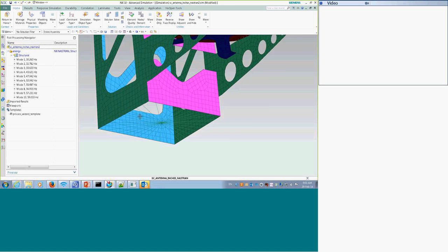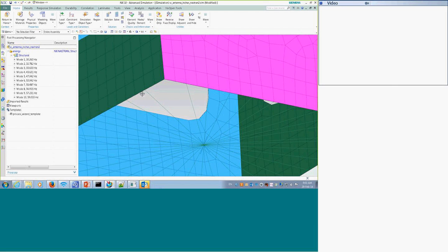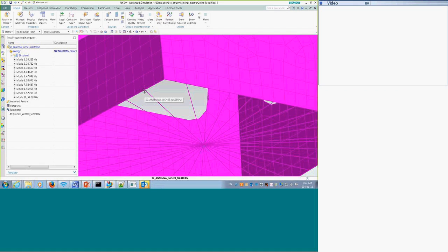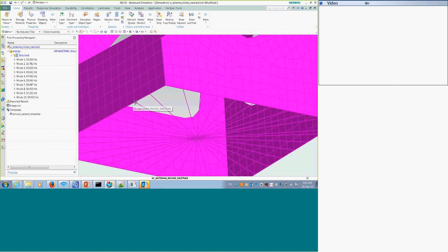What you can do here is you can have beam elements if you want. What we typically use is spring elements between the rigid element and the structure where there's an interface bolt, and we'll see from the random processor extract the forces for those springs. So those could be beam elements, or it could be MPC forces. If you ask for MPC force output, you will get force at these nodes here, and you could use those. Okay, thanks.